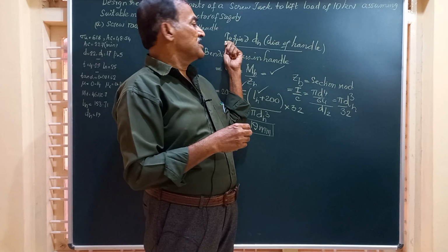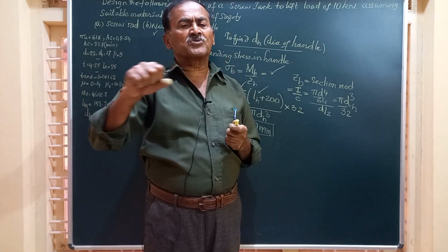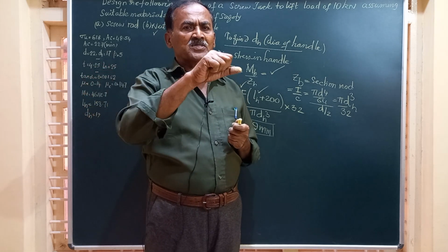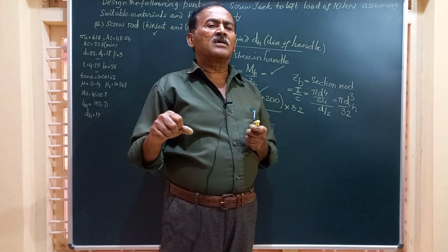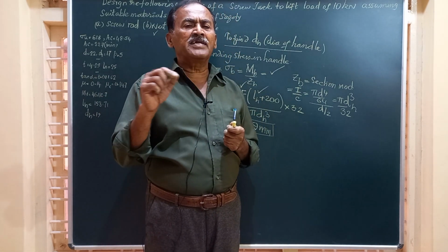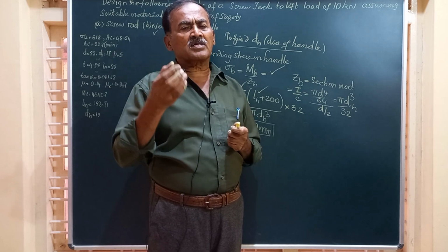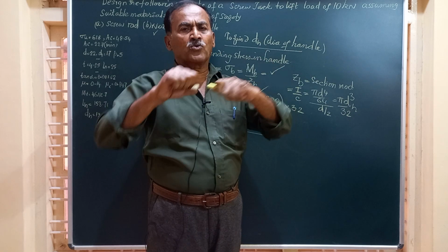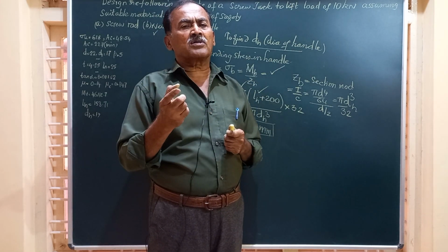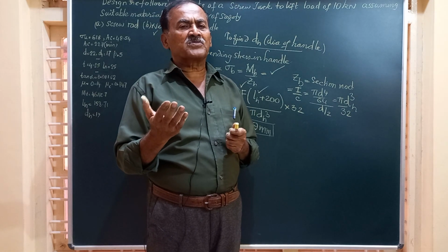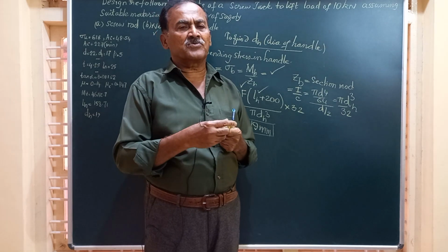And finally, friends, the rod that is designed, rod is also called Tommy bar or the lever used to operate the jack. So friends, there we are going to design the component by finding out what is the bending moment this is to withstand. So it will have a circular cross section which becomes easy for holding and applying the effort, and that is designed based on some assumption of the effort that a human can apply, a healthy person, like 300 to 400 Newton.